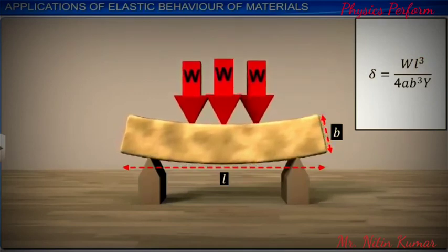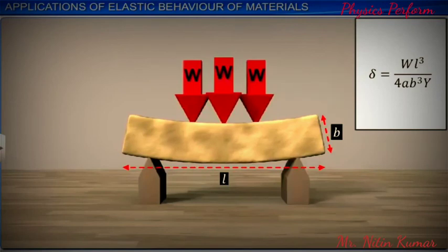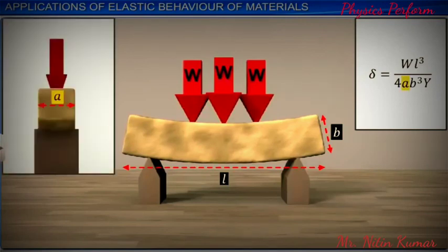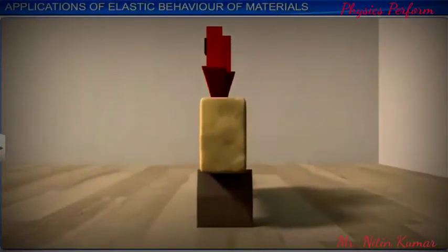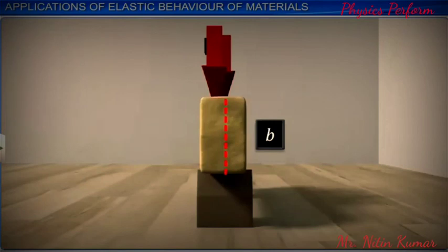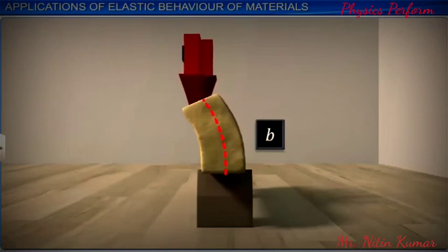Also, as the deflection of the beam is inversely proportional to just the single power of the thickness of the beam compared to the cube of width, the thickness of the beam does not have as great an effect on the maximum load that can be supported as the width. But on increasing the width B, unless the load is placed at the right place, there is every chance that the beam will bend as shown. Such bending is called buckling.